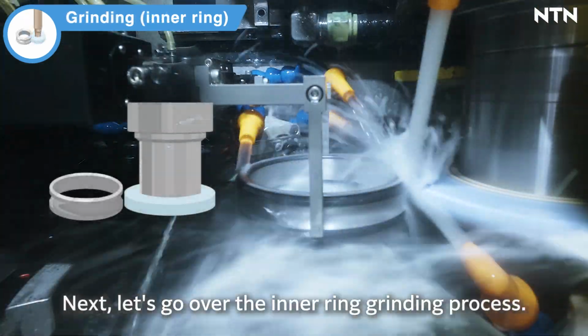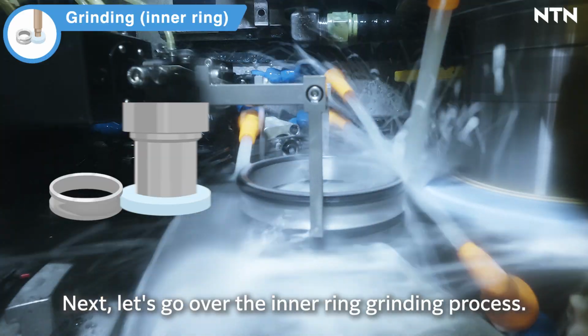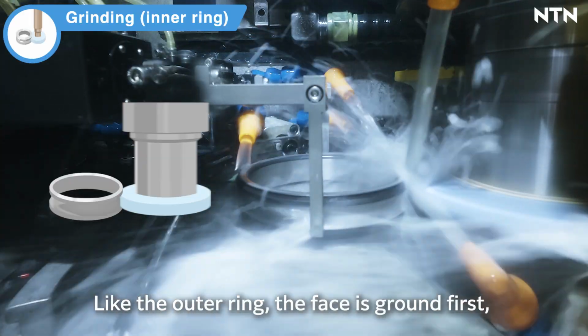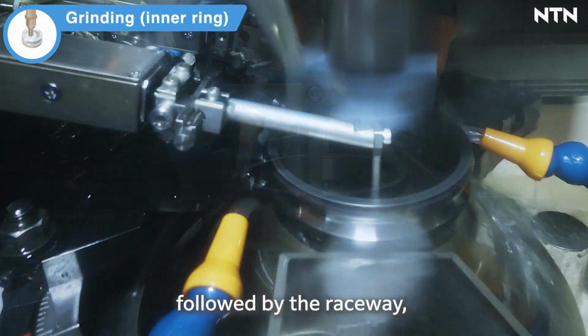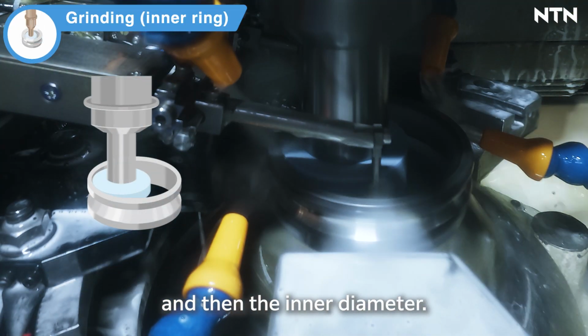Next, let's go over the inner ring grinding process. Like the outer ring, the face is ground first, followed by the raceway, and then the inner diameter.